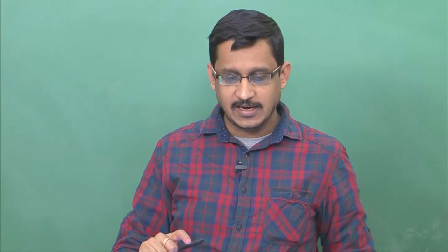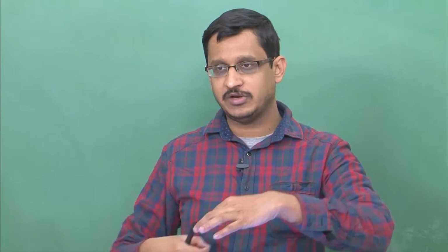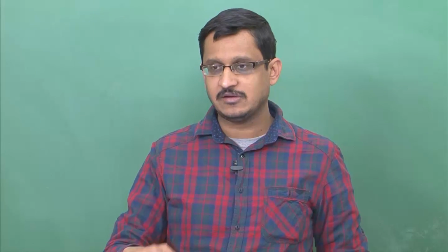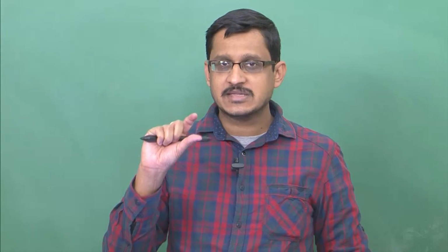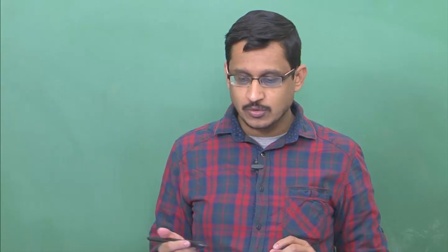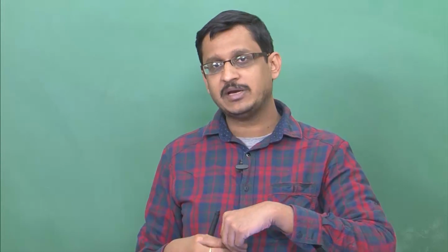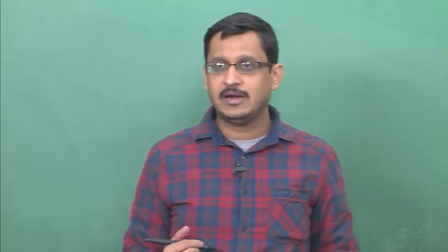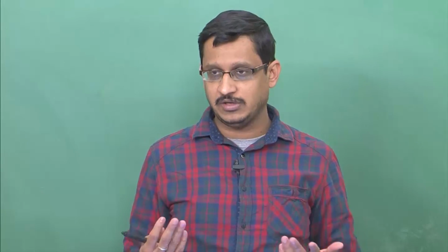Now I can actually take this piece of cross section that I have shown and move it around in the z direction, and if this coaxial cable is infinitely long or at least very, very long, then no matter where I place this surface, I am going to end up with the same amount of flux cutting through this surface, right. If you let z go completely to infinity, then it will not really be okay, because you are now considering an infinite surface area, and the amount of magnetic flux linking an infinite surface area will be infinity, and you will not get any meaningful results.